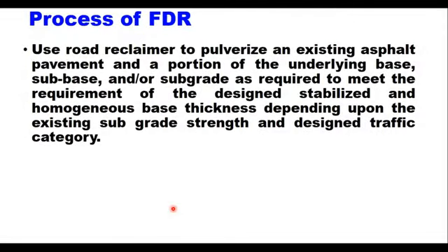The process of FDR is to use a road reclaimer or recycler to pulverize an existing asphalt pavement and a portion of the underlying base, subbase and or subgrade as required to meet the requirement of the designated stabilized and homogeneous base thickness, depending upon the existing subgrade strength and designed traffic category.